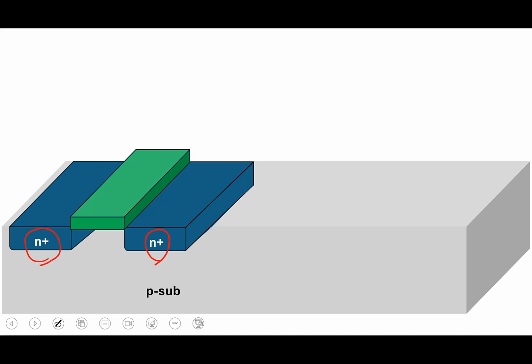Okay, so let's start with how things are made on a CMOS process. Let's start with our hero or heroine, the NMOS and PMOS transistors. How do you think an NMOS transistor is made? Some of you must have taken courses on device fabrication, semiconductor devices. What is the base on which things are made? You have a p-type substrate, on which you put 2 n plus regions. One acts like the source, the other acts like the drain, and this is your gate.